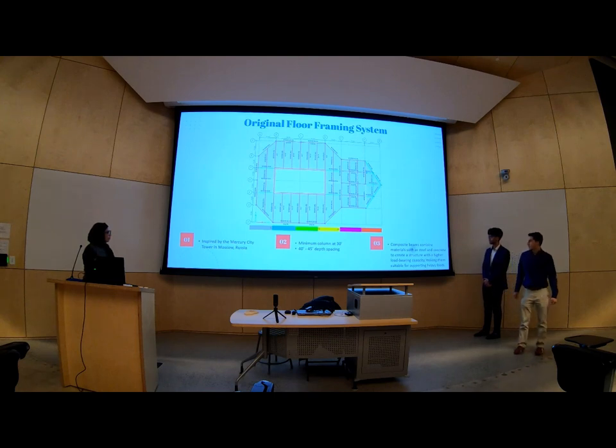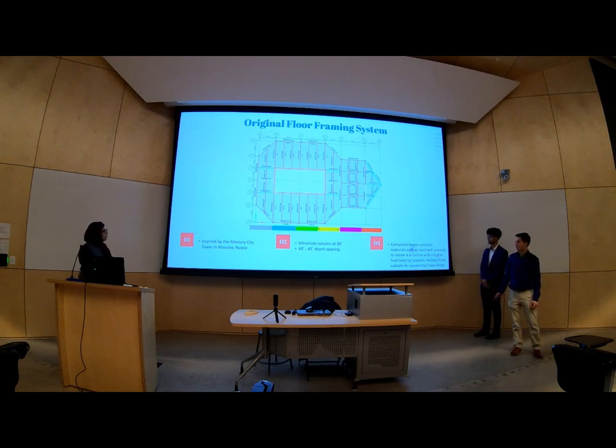We use composite beams, which are beams that combine materials such as steel and concrete to create a structure with a higher load-bearing resistance and make it more suitable for heavier loads. As you can see in the drawing, originally all our beams were optimized to have a stress ratio between 0.9 and 1.0. This was computed through ETABS. So ETABS doesn't take into consideration the construction of the actual tower. So it gives all the different beams, with various different beam sizes to get as close to the ultimate stress that it needs to withstand.